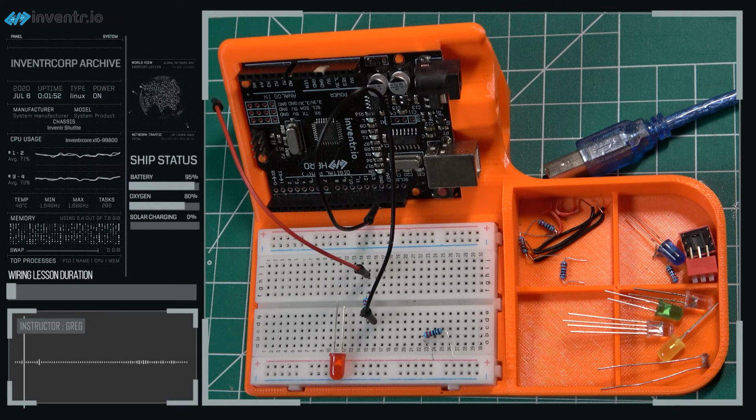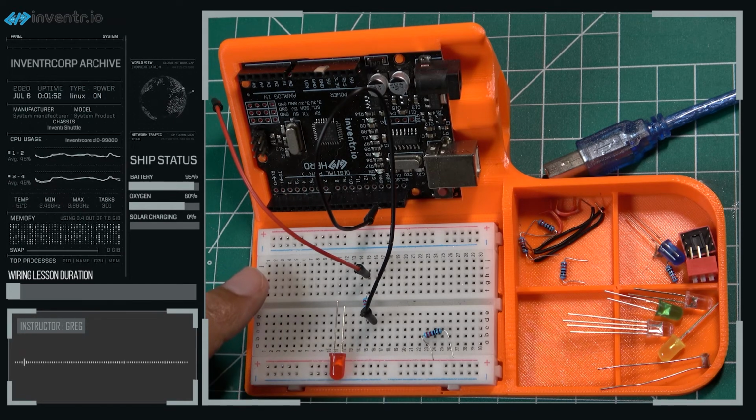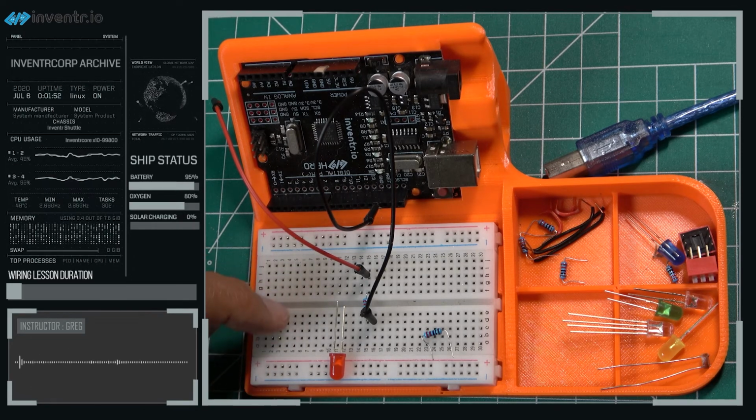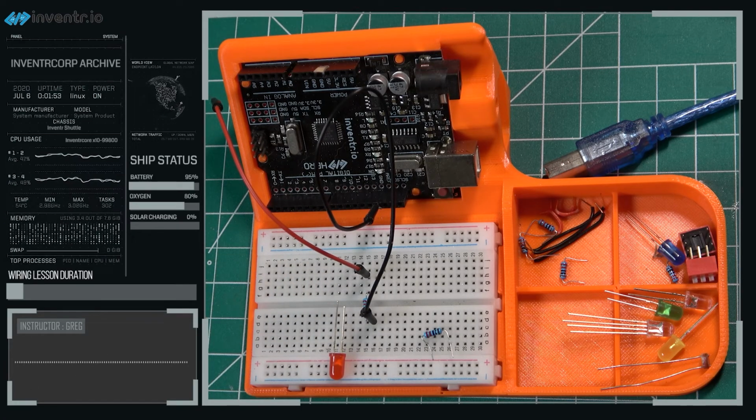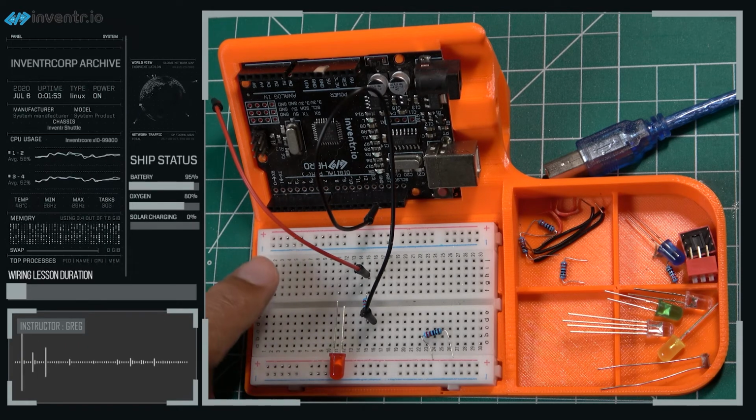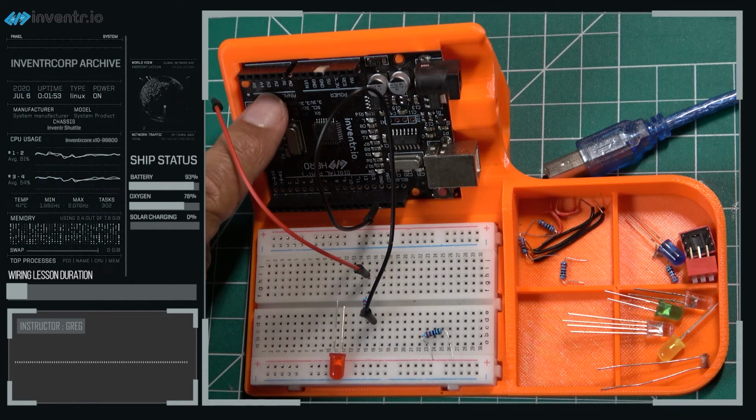Today's example will be very simple and basic, but before we jump into it, let's just say a few words about our workstation. Generally speaking, we'll be assembling our analog circuit components on this white plastic breadboard. The internal electrical connections along the numbered columns of the middle part of the breadboard provide a convenient framework for quickly connecting components to each other and, by using jumper wires like this, connecting to our Hero digital controller, which is up here above.